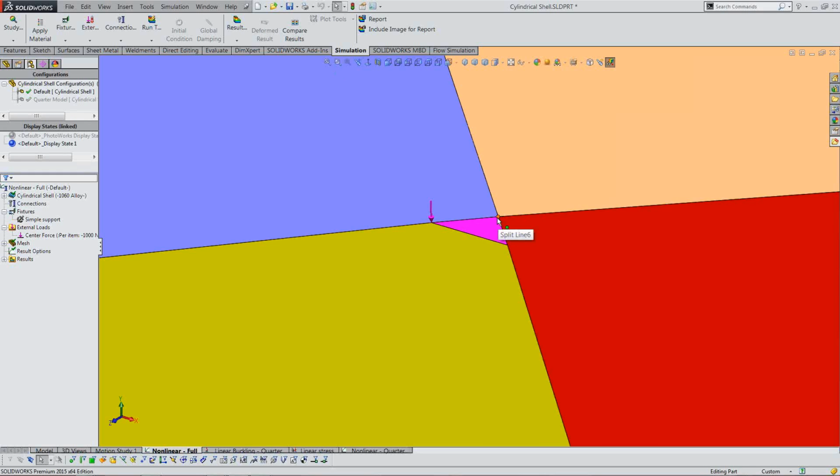So it was a symmetric problem in terms of loading. In the second case, the load has been moved out to a vertex slightly off-center to introduce some more nonlinearity to the problem. And the force has been quadrupled because now this is no longer a quarter symmetry problem. We're looking at the full sheet, so it's actually an equivalent force of 1,000 newtons.